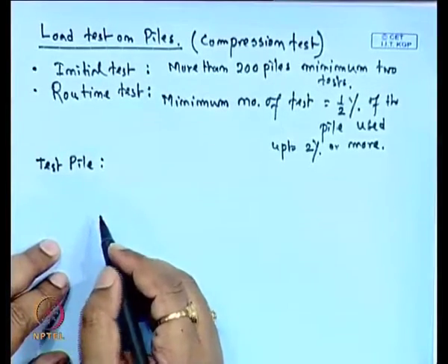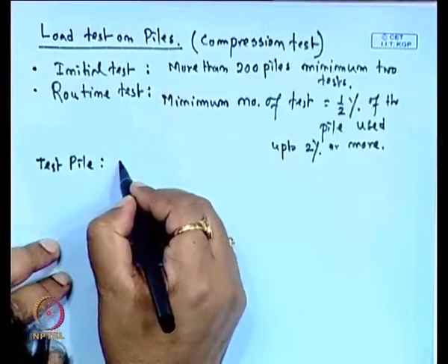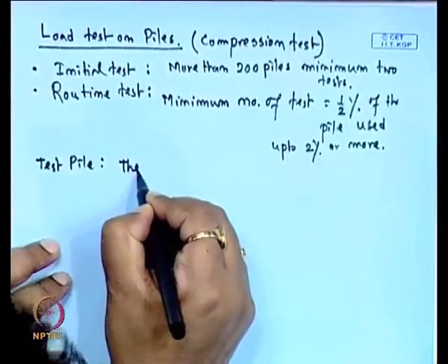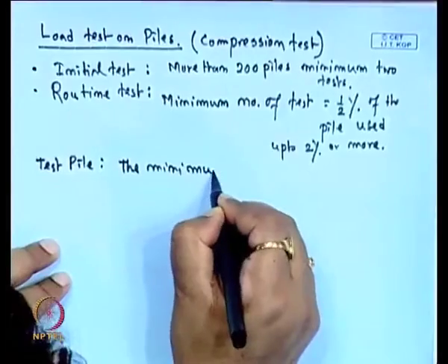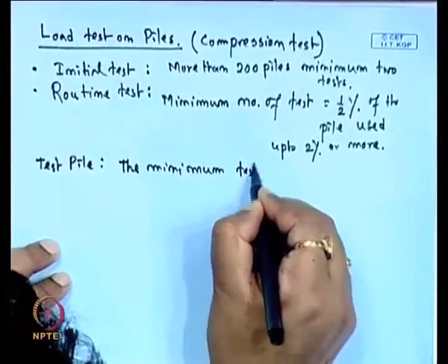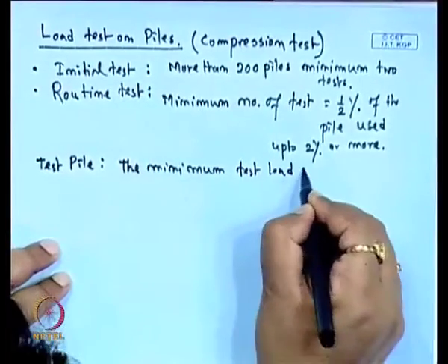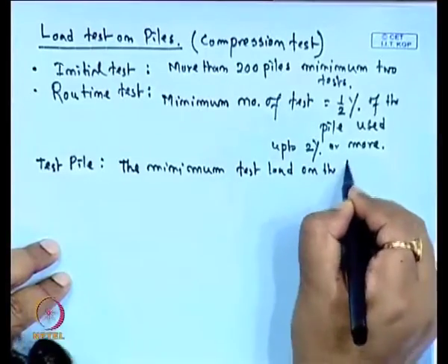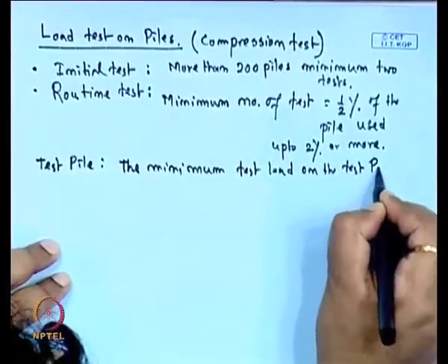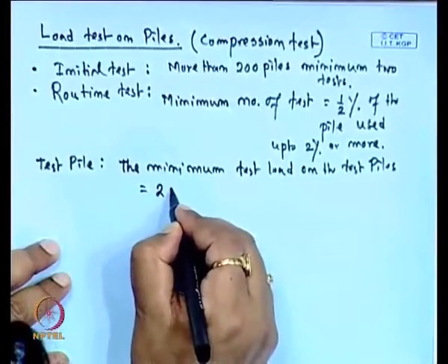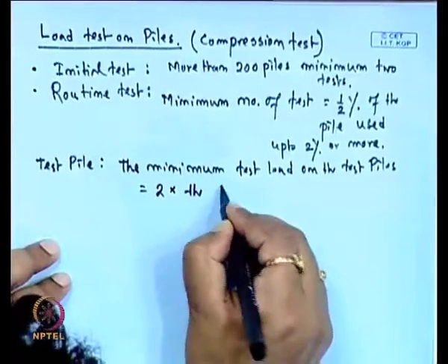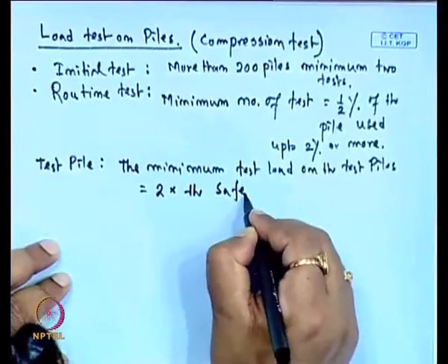Now, the minimum test load on the test pile is equal to 2 times the safe load.